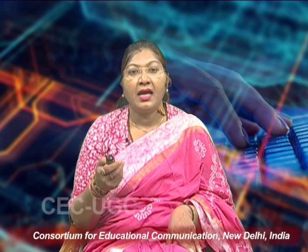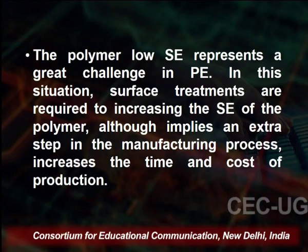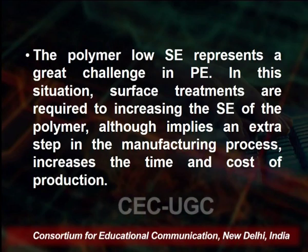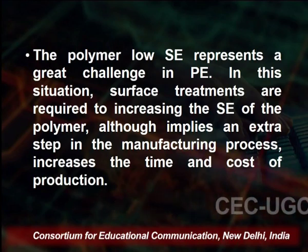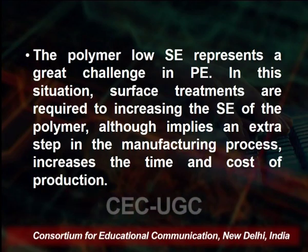Adhesion between the solid and liquid is exhibited when the solid surface energy exceeds the liquid surface tension. So in polymers, low surface energy represents a greater challenge in printed electronics. Surface treatments are required to increase the surface energy of the polymer, although it implies an extra step in the manufacturing process, increasing the time and cost of production.